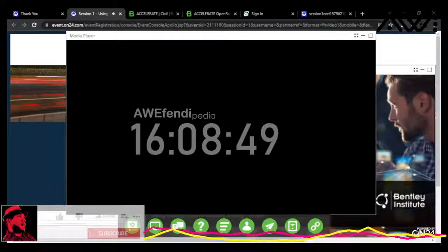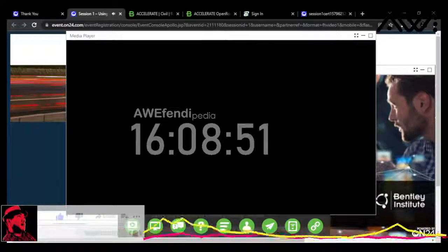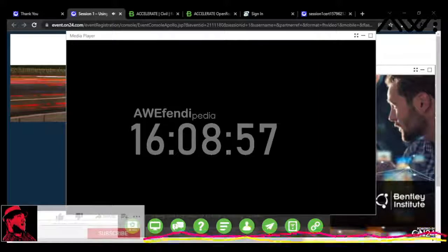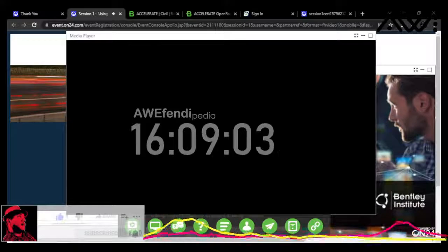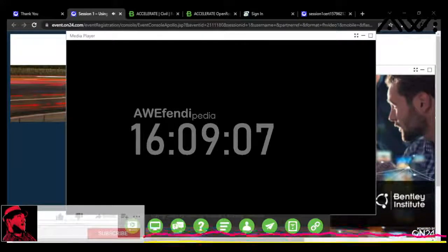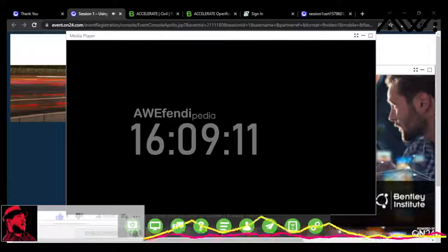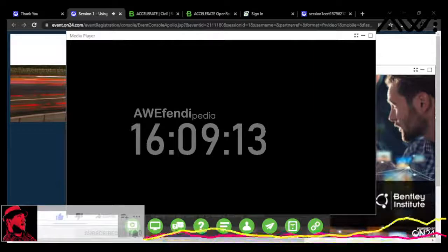I can come in and click on that slope distance. I can make it 700, and we'll see the point pull in closer to the setup. I can come in and change the angle. If there's any reason where I actually have to change the observation data, I can make it 165, and I can see that point move down to 165. So I can edit anything graphically, and that's why we see these observation manipulators here.